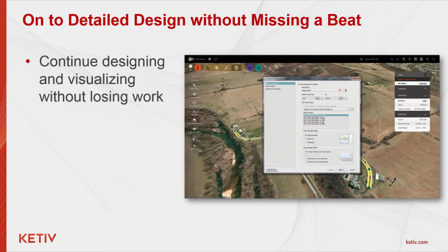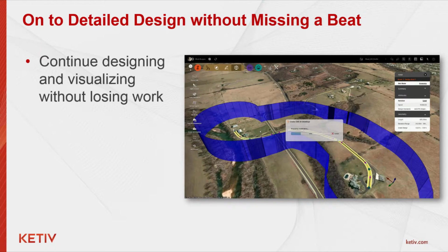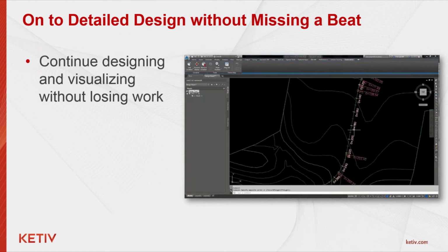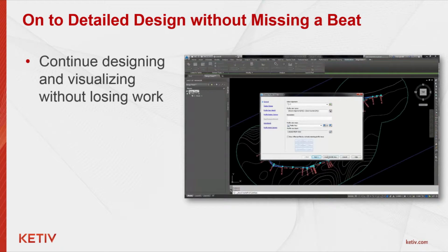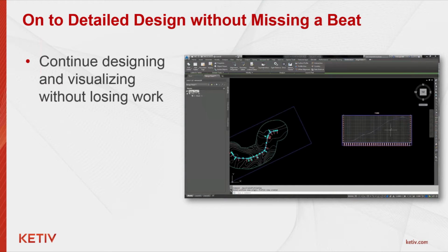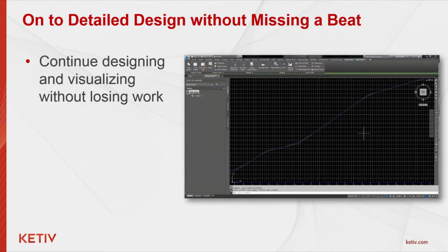All right, so then this might touch upon what you were talking about, Eric. What you can do in InfraWorks, you can generate pretty much Civil 3D drawings from a road model by bringing that into Civil 3D. So it creates design drawings plus an entire sheet set for you. You can then open up InfraWorks 360 models in AutoCAD Civil 3D, easy like that. You can just open them right up and view what you did for your preliminary design, and then move on to the more detailed portion.